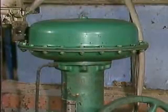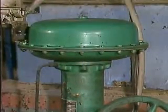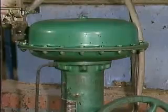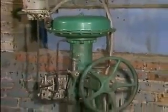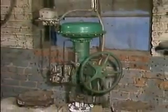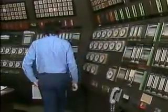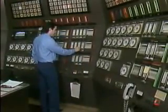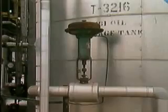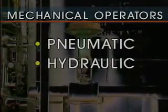But valves often use mechanical operators or actuators to open and close. With these devices, valves can be turned on, off, or throttled more quickly and easily than with manually operated devices. Also, when mechanical operators are used, valves can be repositioned from a central, remote location, such as a control room. Common types of mechanical operators include pneumatic, hydraulic, and electric.